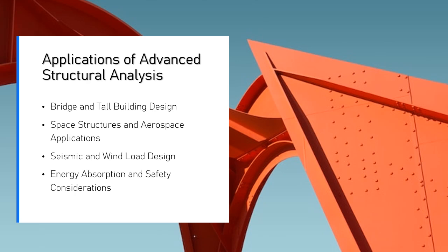failing structurally. Advanced design. Crash barriers are designed using energy-absorbing materials like high-tensile steel, concrete, and composite materials that deform upon impact. Advanced analysis methods, including finite element impact simulations, are used to optimize the design and ensure energy dissipation while preserving the integrity of the bridge structure.